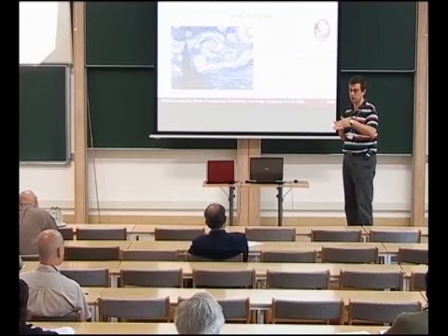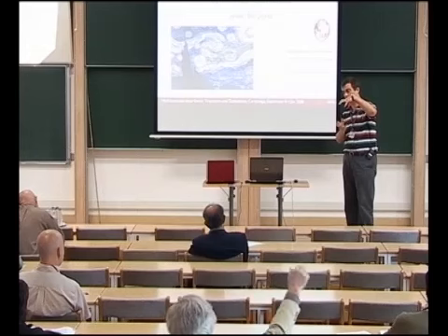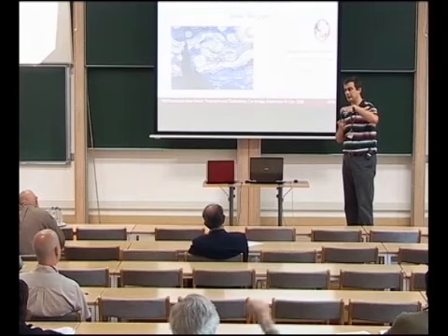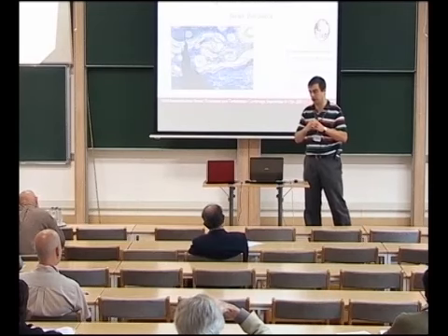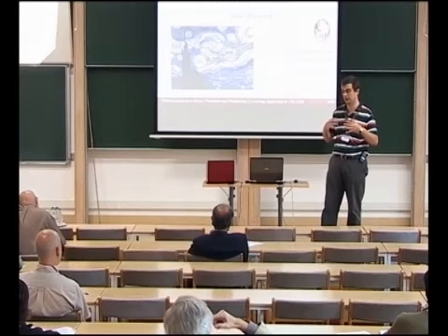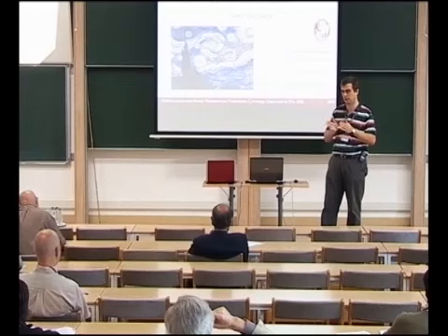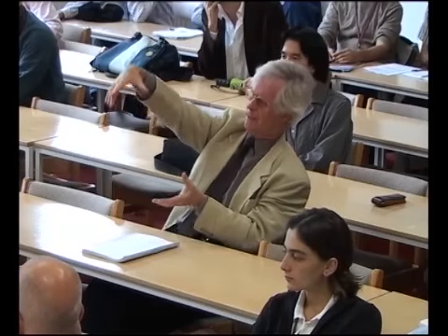You may obtain, for example, a symmetrical velocity field that remains for very large Reynolds number, or you may find something that François Javier showed yesterday, a transition from a two-cellular flow to one big cell in the system. Then the dynamics really depends on the shape of the impeller. But the shape of the impeller controls the ratio between the different components of the mean velocity field. And that's the parameter here, how the shear layer.